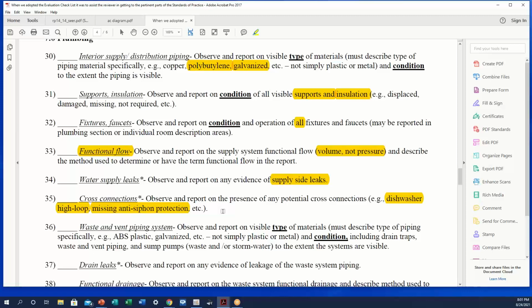Real quick, Brick. Who is it? I didn't get burned, but a contractor schooled me on a new build. I used to think that ABP with the arrow meant anti-back pressure, and it wasn't. It was an actual Arrow brand product. The ones that have the built-in anti-siphon are an Arrow brand product solely, and they also say, like Brick said, anti-siphon right there, usually painted over multiple times.